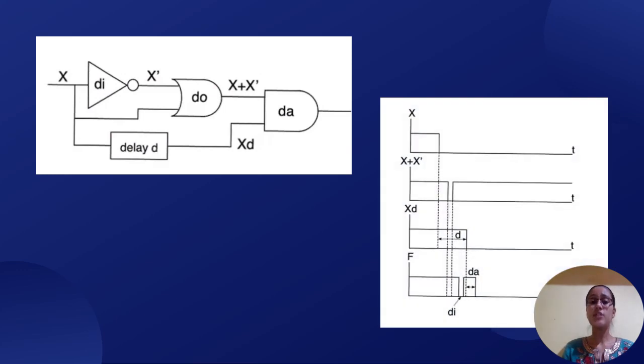So this is the circuit where we can see the static one hazard also, which is an implicit static one hazard, due to which dynamic hazard occurs. As I told you, A A bar is the condition for static zero hazard, and the dynamic hazard expression I have also told. So this is the condition of static one hazard.